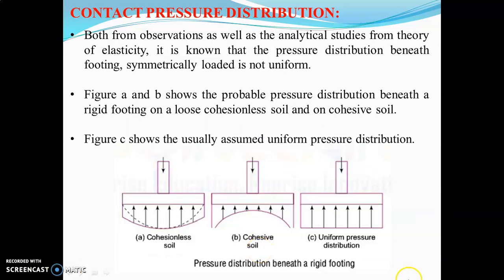And figure C shows the usually assumed uniform pressure distribution. Actually, the pressure distribution is like this for cohesionless soil, and this is for cohesive soil. But for design purposes, we consider the uniform pressure distribution. Like this, we assume and we design.